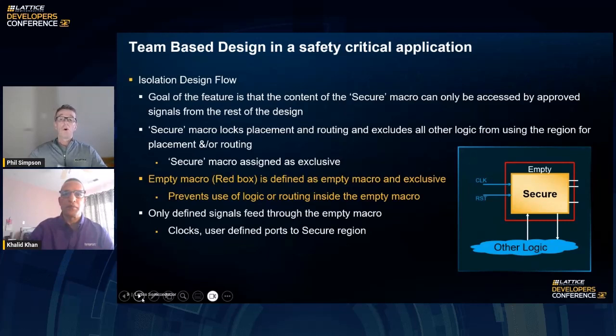Typically a single user will work on that secure block. He will implement it with the floor plan constraints and close timing. If the user has met their timing requirements, hopefully with a margin of 10 to 20%, they will then lock the place and route. And then this locked place and route will be used in the project for the rest of the compiles, where the rest of the logic may still be developed or may still be changing. So one of the key aspects here is floor planning and closing timing.